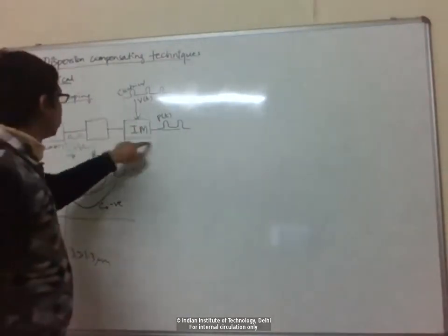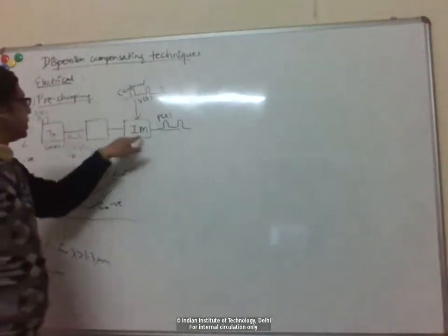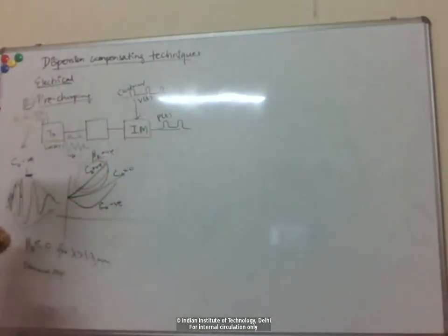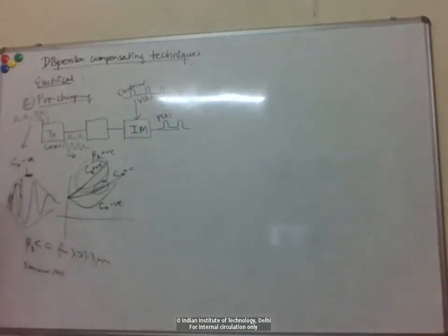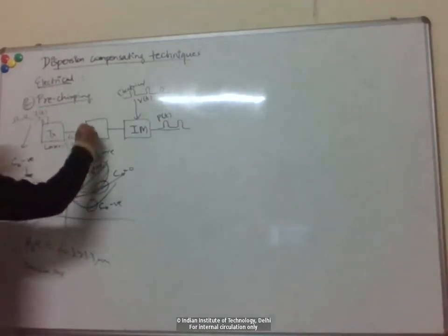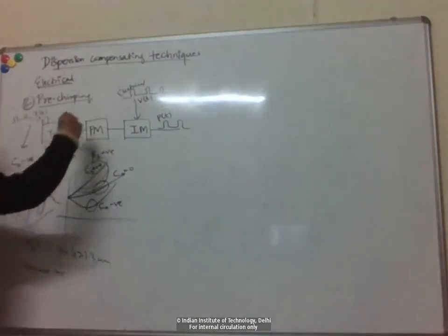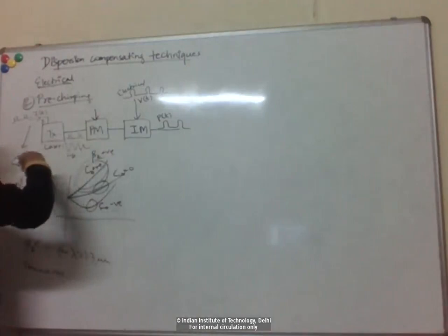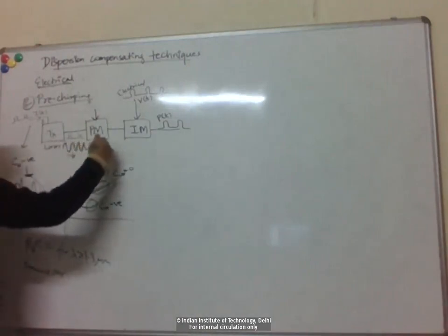So basically we use an external modulator. An external intensity modulator does not give any chirp, so then you go to this middle case. But again, for very long haul systems, we want to do even better, so we want to go to this case. What we do is we have a phase modulator, and we use the phase modulator here to chirp this carrier wave.